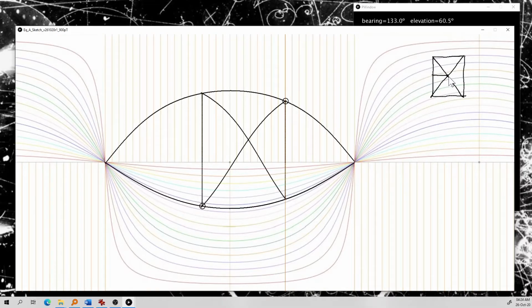Now, if I pass a horizontal here that is a parallel to the top and bottom of the wall, and a vertical, and then I do another X right here, well, this is a rectangle that has the same proportions as this big one. Okay, so I'm further subdividing the rectangle, and I could do it again and again to get a uniform division of this rectangle that would work as a grid wherein I could locate with any precision desired any pattern or point that I wish to locate.